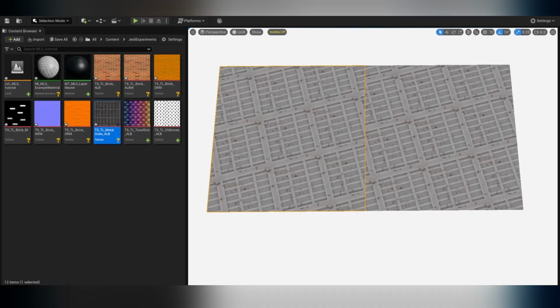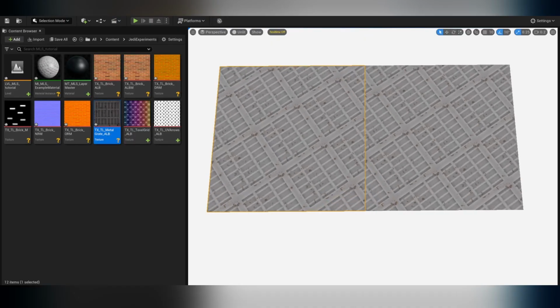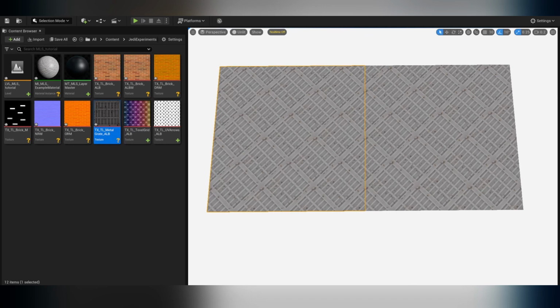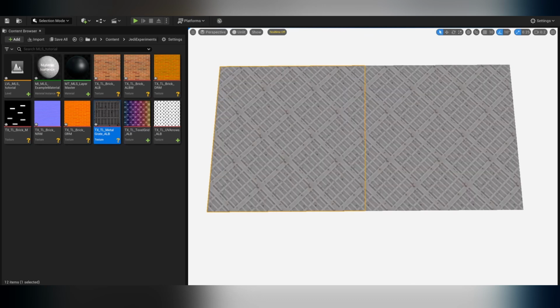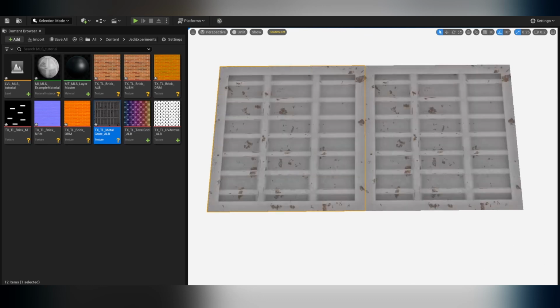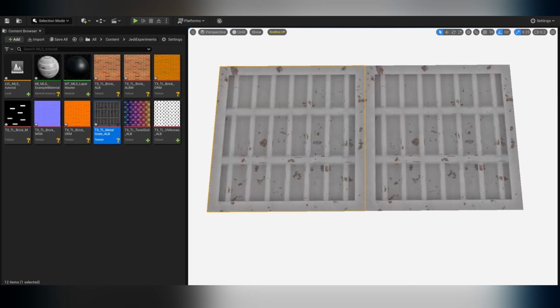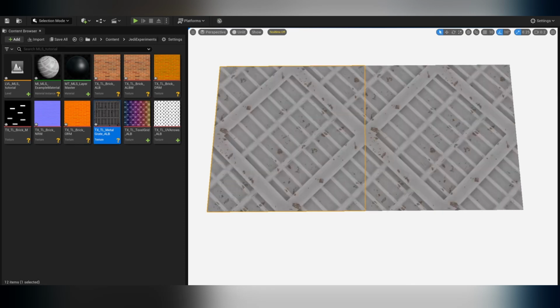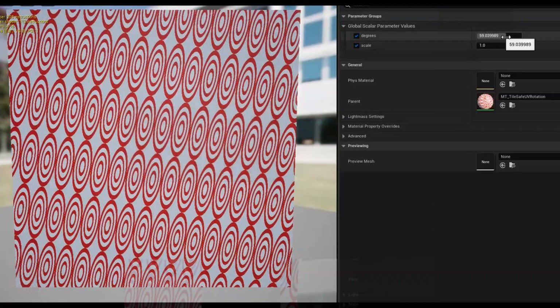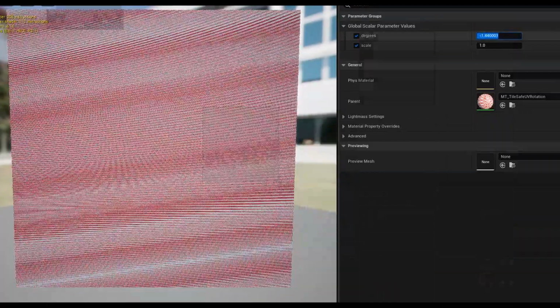This may be a niche issue, but if you need to tile across mesh seams and want to retain texture seamlessness when rotating the texture, enabling bTileSafeRotation will snap the texture in 45-degree increments to preserve seamlessness. Smaller degrees of rotation are possible, but the scale and aspect ratio distortions that arise make it not viable.